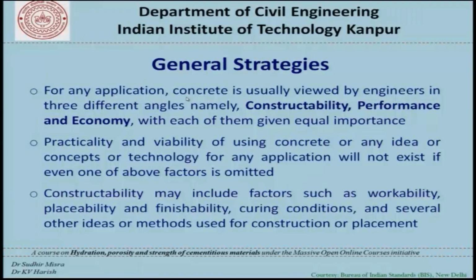For any application, concrete is usually viewed by engineers from 3 different angles, namely constructability, performance and economy. Remember that each one of them is given equal importance. The practicality and viability of using concrete or any idea or concept or technology for any application will not exist if even one of the above factors is omitted. Constructability may include factors such as workability, placeability, finishability, curing conditions and several other ideas or methods used for construction or placement.